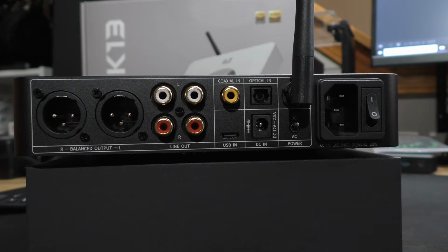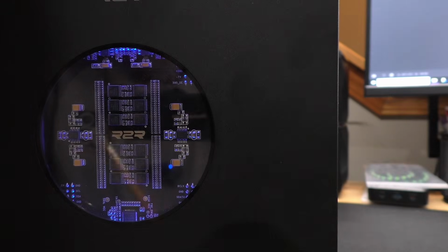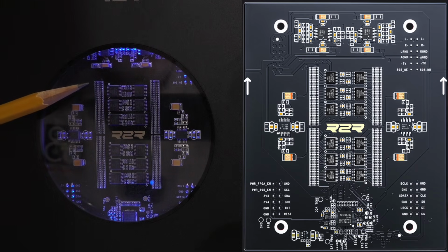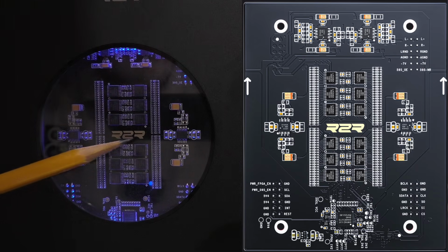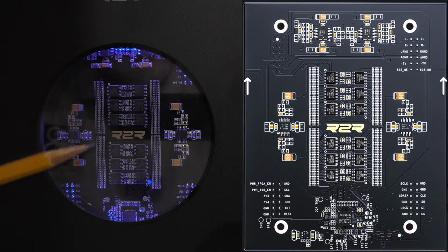So let's take a look at the top of the unit and the inside so you get an idea of what that R2R ladder configuration looks like. Well, there you can see the inside of the unit. I will also put a closer photograph of the R2R ladder configuration. But the key things are, as you can see, and it's got the lovely little LED light in it, there are 48 resistors and there's actually 4 rows of 48, again, total of 192. And that gives you the fully differential balance.